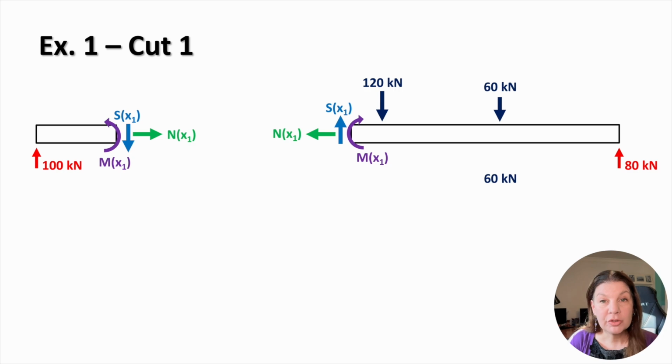Matching internal forces to balance these out will develop on the other side of the cut. Note that the forces will be equal but opposite in direction, so that when we close the cut, they'll disappear. They are internal forces, right? It's important to remain consistent here. The directions we assume will determine the signs of the results. We isolate the left-hand side of the beam and draw the free body diagram, including the support reaction and the internal forces at the cut.